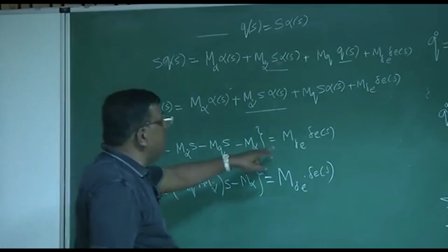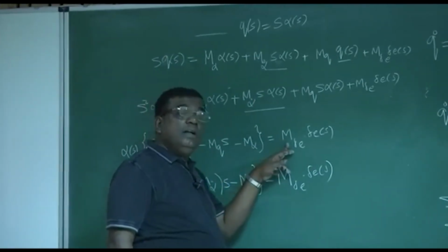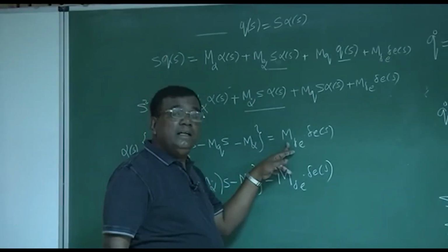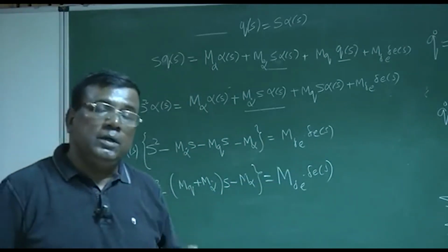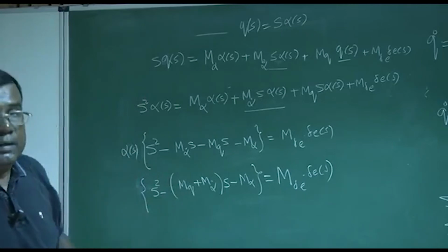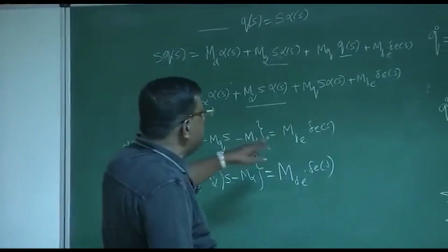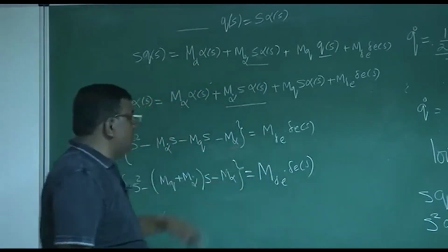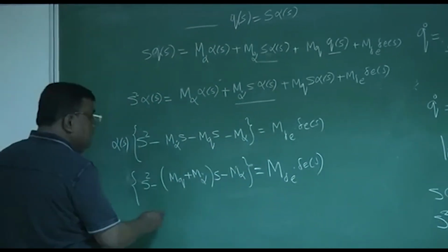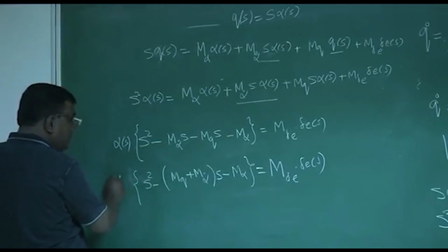When I think of M delta E, immediately I know the non-dimensional derivative is Cm delta E. That is, what is the increase in Cm because of elevator deflection, whose sign is negative. And this is dimensional, but Cm delta E is non-dimensional, right? So you know these expressions. So now I can write this as, here alpha S has to come.